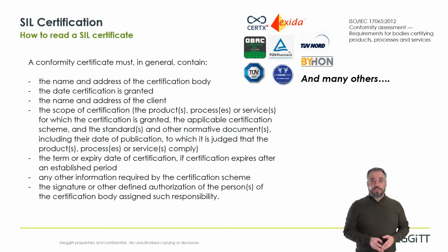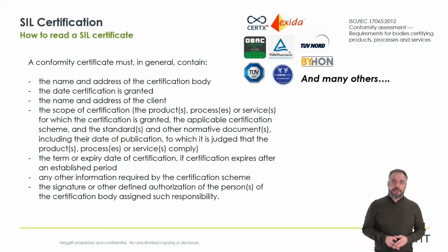Let's now take a look into SIL certificates. There are many certification bodies that can release a certificate of conformity, and all follow the same rules. When a certified body provides a formal certification document, this document, according to IEC61508, which is the standard that regulates conformity assessments, must contain a well-defined set of information. This set of obligatory information is not very extensive.